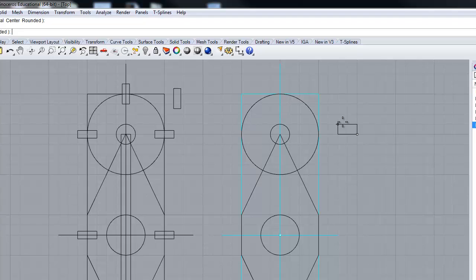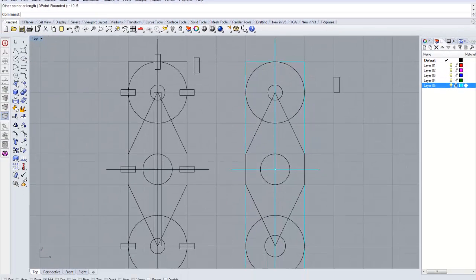And what's nice about arraying these in the end is that you only have to go back and fix your unit form. So for right now, I'm going to go R, because I want to do it relative. And I'm going to do 0.19, comma, 0.5. It's going to make it a 1/2 inch, and it looks something like that. Now, with my mid-snap turned on, I can do a copy or a move. You can either move or copy. I'm going to select this object, do a copy, go to the midpoint here, and put that down there like that, and notch that like so.